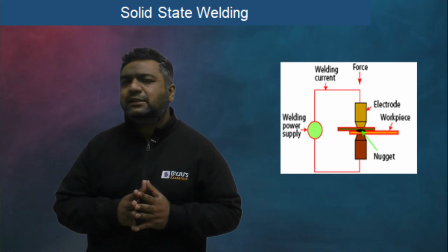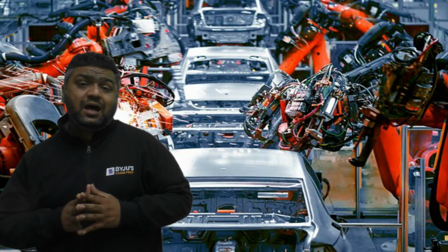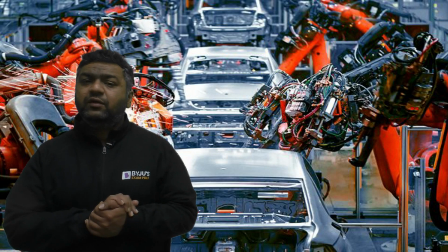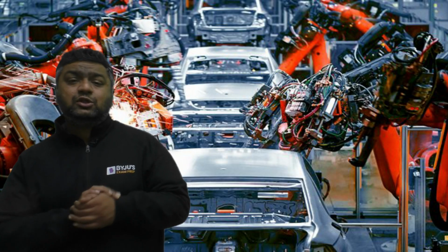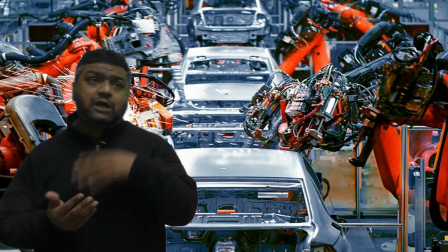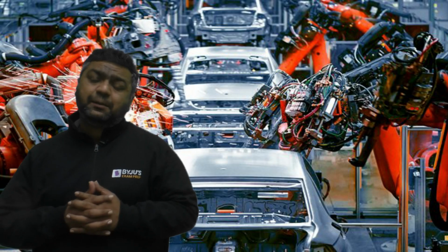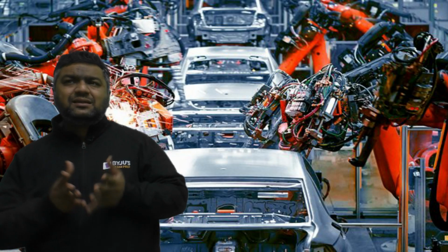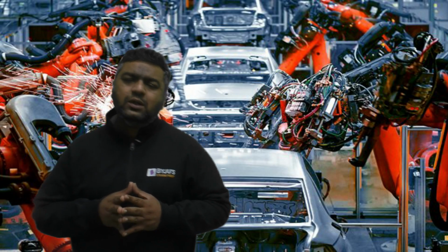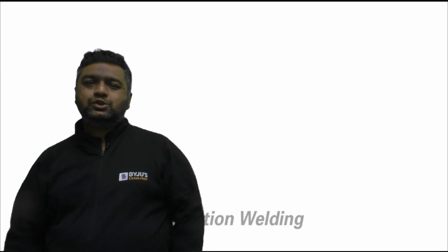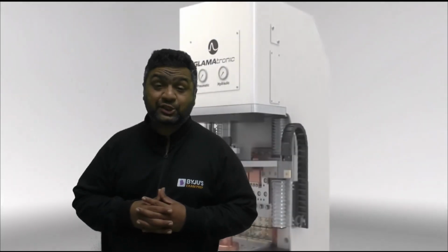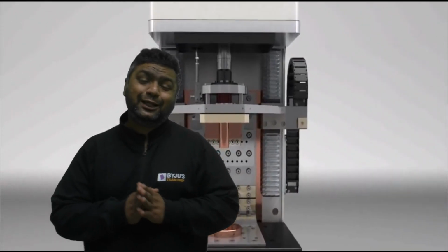Spot welding process is used in automobile industries, and we are using it where we want, you can say, the joints which are sound joints, sound quality welds are performed by this. But this is a discontinuous process, as you know. So when we are talking about the one more process of resistance welding, so the second process is projection welding. It is also said to be the multi-spot welding.